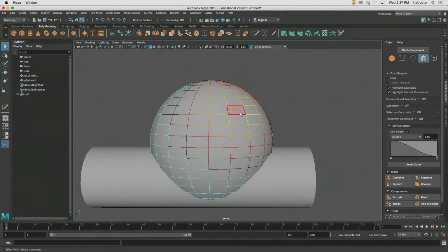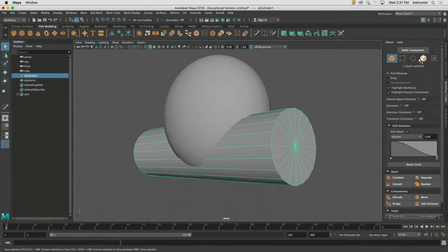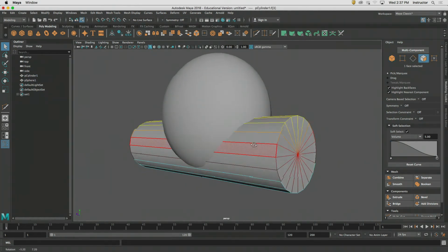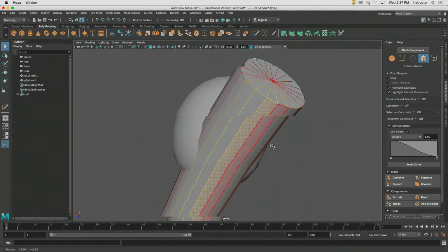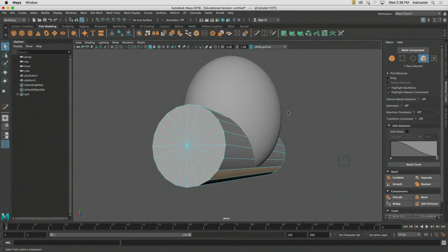And once the soft select system is on, you can see that it's always on, okay? In component mode at least. See, I've gone to a different piece and it's still on, so hit the B key, turn it off, and now our tools are working the way that we want them to.